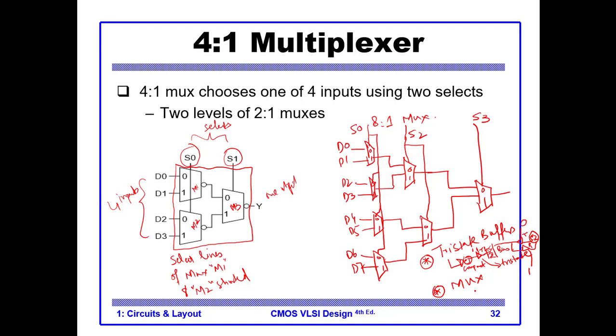But the mux is an interesting element. You can also use the mux for this kind of functionality. If you want to put something on the bus, you can use a mux, because a mux can also connect multiple elements. If you have two components, C1 and C2, and this is your connection to the bus, you can put C1 here and C2 here.